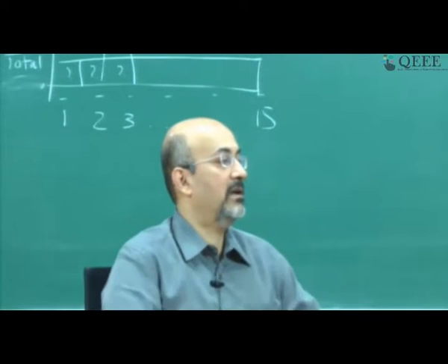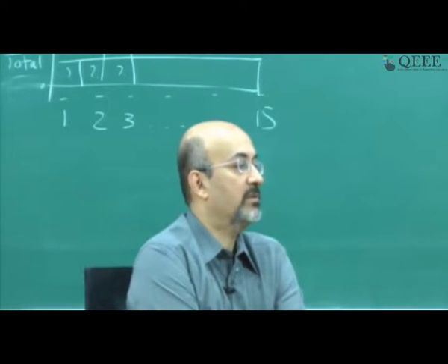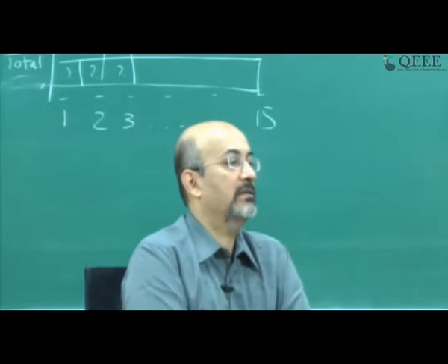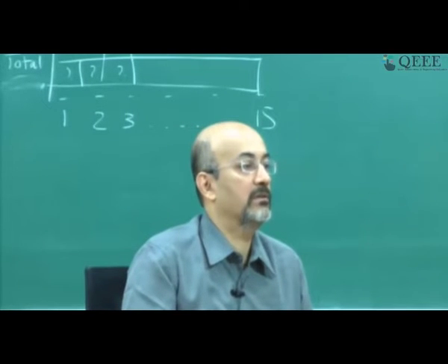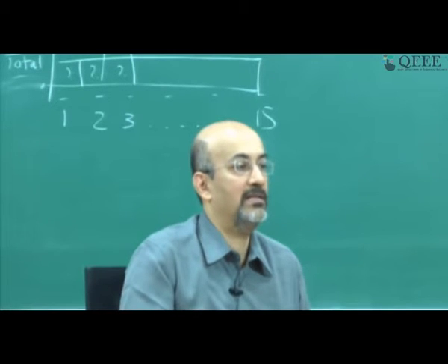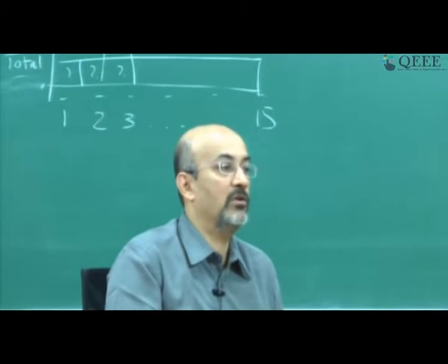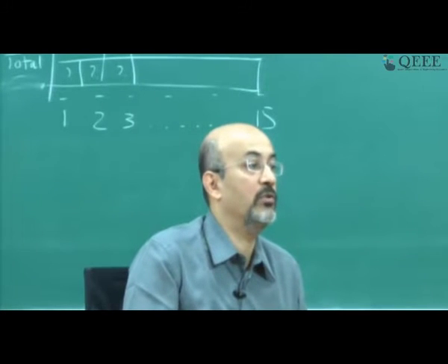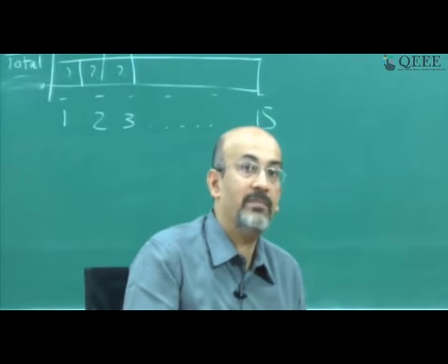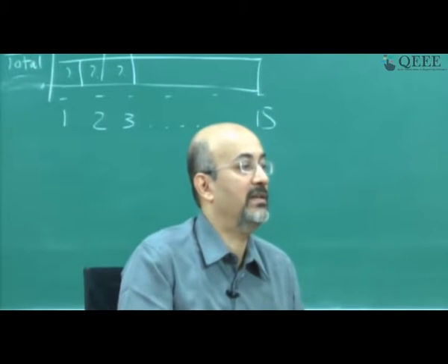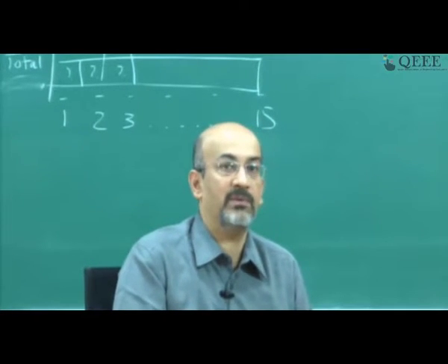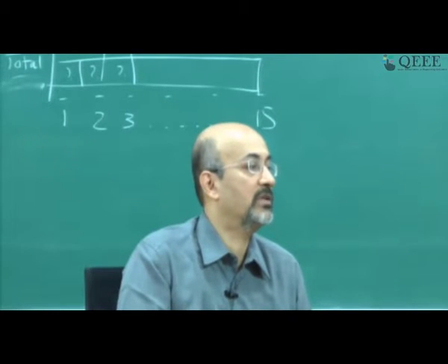I have another question: using early start, is it possible to have many solutions? Certainly the leveling part can have many solutions. Here, what I have shown you, the early start was not an acceptable solution, and the late start was not an acceptable solution. We said this is an acceptable solution, but is it the only one, a unique solution? No, there can be several shifts of activity D or C which can provide an acceptable solution. So this is not a unique solution, and that's a good question.